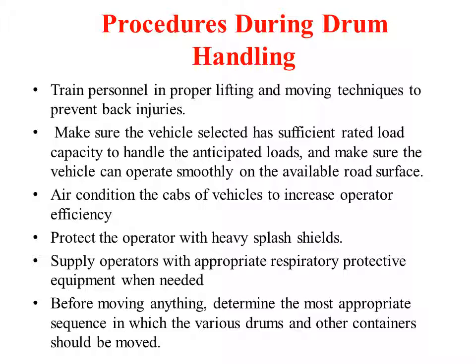We should practice good housekeeping, personal cleanliness, and equipment maintenance. When we say maintain cleanliness at all times in the workplace, it means we should clean up any spills and buildups of corrosives promptly and safely. We should properly dispose of unlabeled or contaminated chemicals. We should remove empty containers at once from the work area.